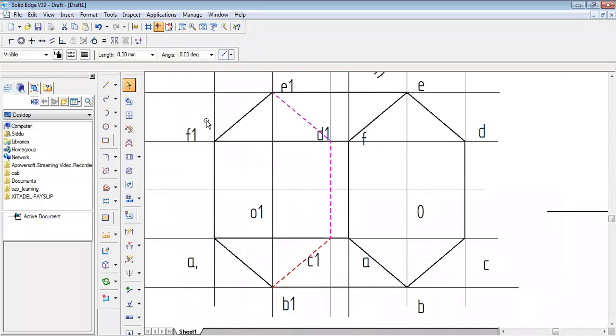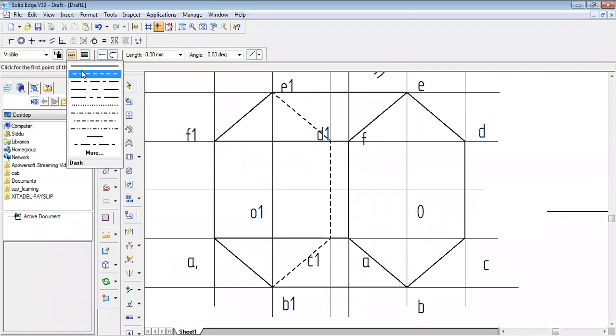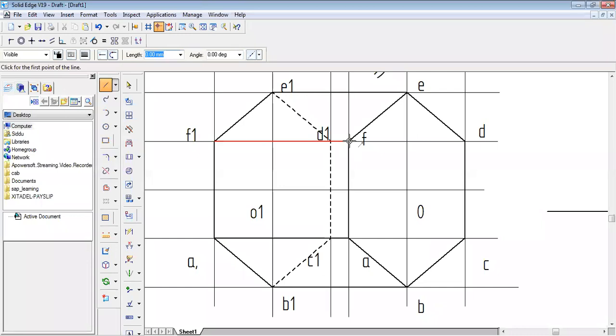But here, while doing it, these two unseen edges have already come across one more edge, that is a seen edge. So now you don't start from here, because one more seen edge is already crossed. So now, leaving that portion from here to here, we will show here as unseen. Hope you are getting the point,